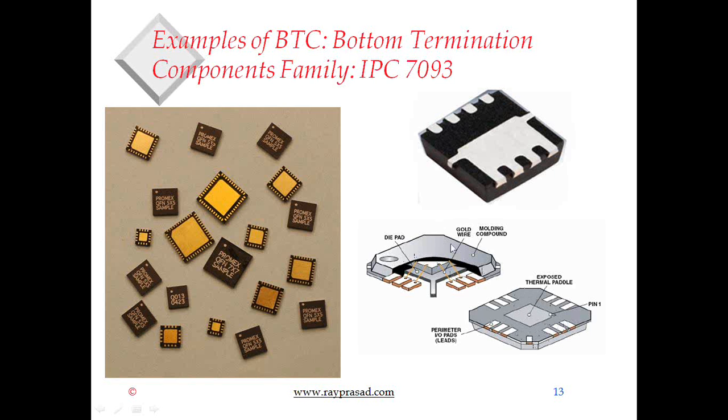And the one in the middle basically shows you the lead frame where the outer leads are and the center thermal pad, and you have a silicon that's placed on the thermal pad and wire bonded to these outer leads. So essentially, think of a sheet of copper, and that's what it is.